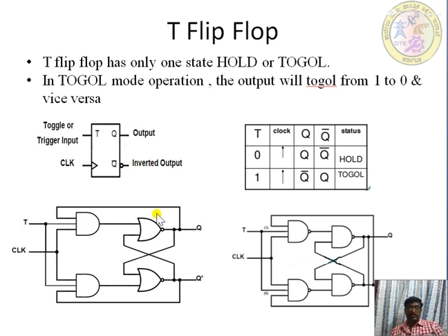So this is the end of these flip-flops. Next we will go through the JK flip-flop. Why do people go for the JK flip-flop? Just to overcome the forbidden state that we get for the fourth state in an SR flip-flop. In a normal JK flip-flop we come across the race around condition. To overcome that race around condition, we go for the master slave JK flip-flop.